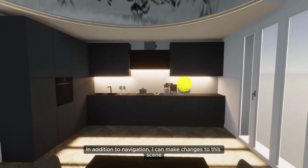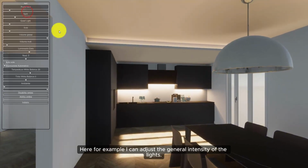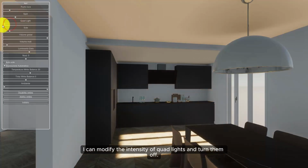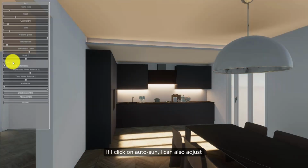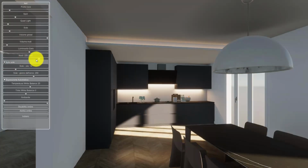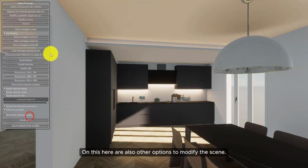In addition to navigation, I can make changes to this scene, clicking the left mouse button. Here, for example, I can adjust the general intensity of the lights. I can modify the intensity of quad lights and turn them off. I can modify the parameter sun. If I click on auto sun, I can also adjust the direction of sunlight, increase environment light. On this here are also other options to modify the scene.